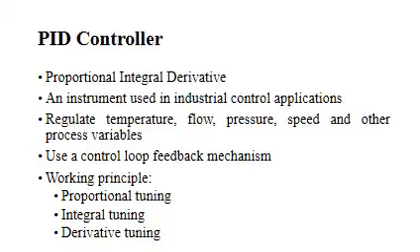Derivative tuning attempts to minimize the overshoot by slowing the correction factor applied as the target is approached. The PID controller is used in some systems with relatively low noise level in the measuring channel. The advantage of PID is fast warm-up time, accurate set point temperature control, and fast reaction to disturbance. Manual tuning of PID is extremely complex, so it is recommended to use the auto tune function.